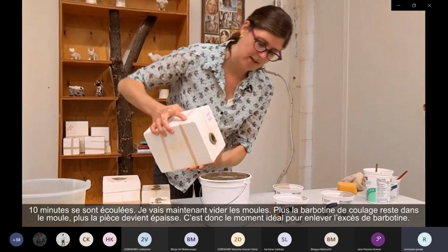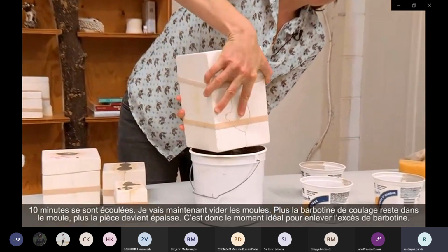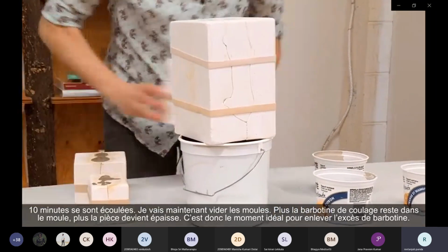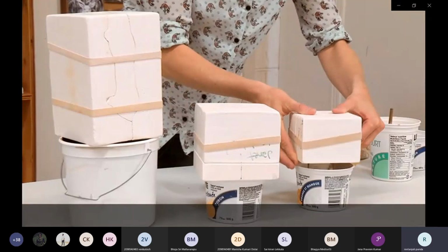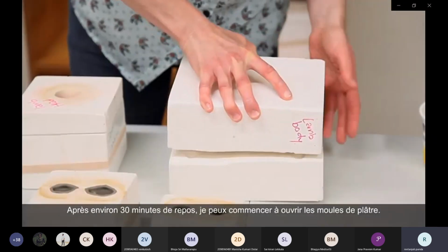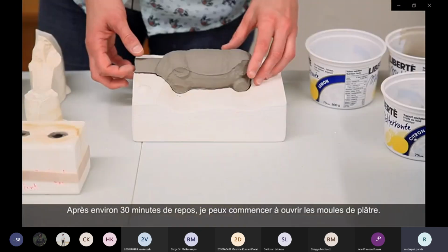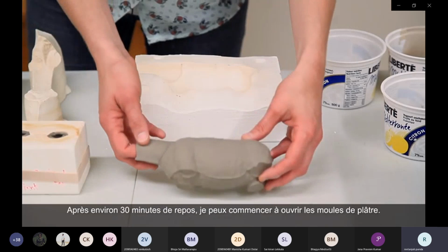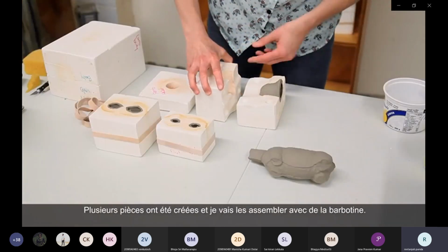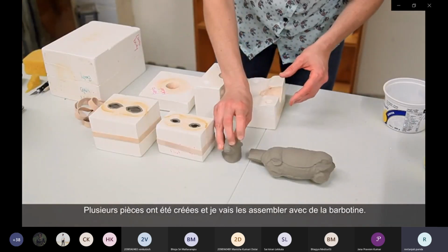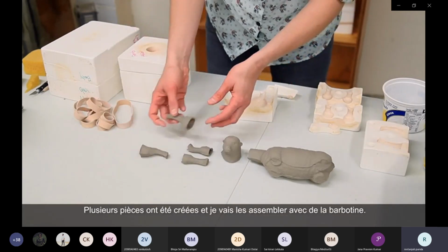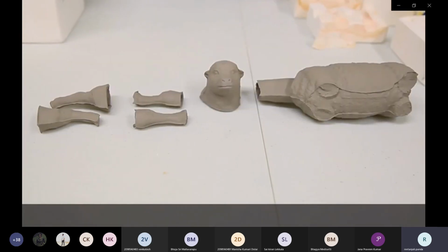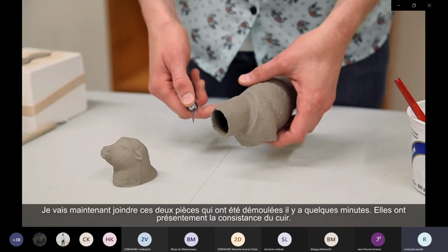So she is taking out the extra non-solidified ceramic liquid from every container. After some time they remove the molds, and what they receive are different structures that are hollow by nature. That is the ceramic. This is the slip casting process.